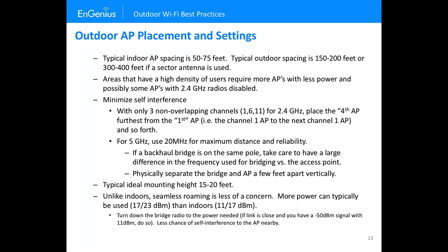Also, there's this issue where you get RF shadowing. The antennas, even though they're on the vertical beam width, I call it the Pac-Man's mouth, how wide he opens his mouth, is the vertical elevation of an antenna radiation pattern. You could actually overshoot your people below you. So don't mount it too high. You could mount it probably 25, 30, but really high, it's not going to work too well. You're going to be further from your clients.